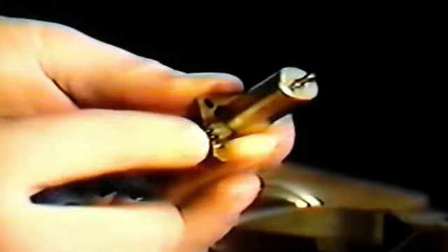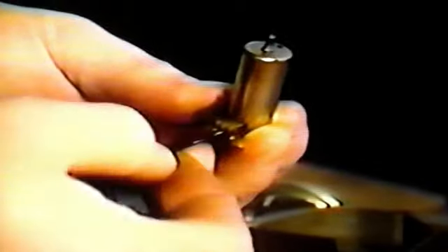The second place to inspect is the wires in the unit. Here, you'll be looking for insulation oozing around the wires, a very damaging set of circumstances. The last thing you should check for is pinched wires with copper showing. This is a potential source of shorting or voltage loss. Again, if you find any one of these three problems, you must replace the MCS.